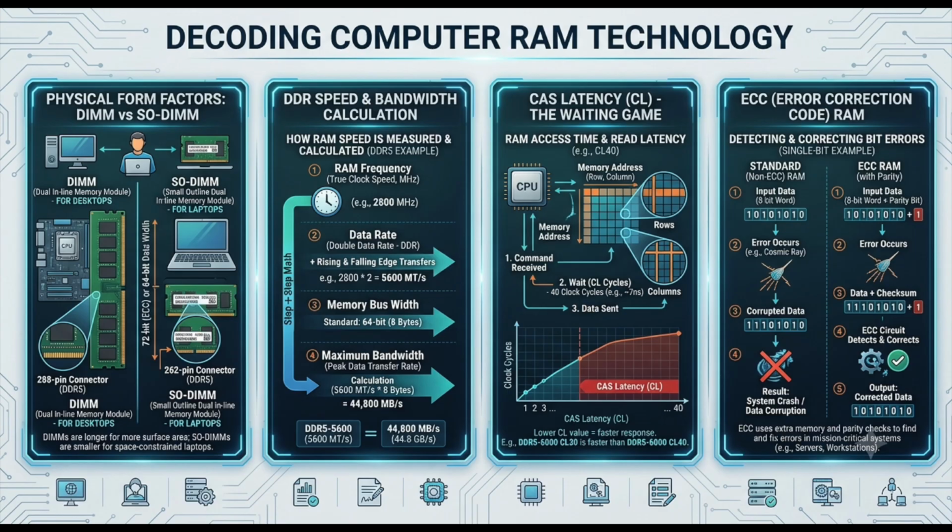So physically, we know RAM isn't just a bunch of loose chips scattered across the motherboard. It's this highly engineered module. And the industry term is a DIMM, right? D-I-M-M. Yes, DIMM, which stands for Dual Inline Memory Module. Dual inline. What does the dual part actually signify there?